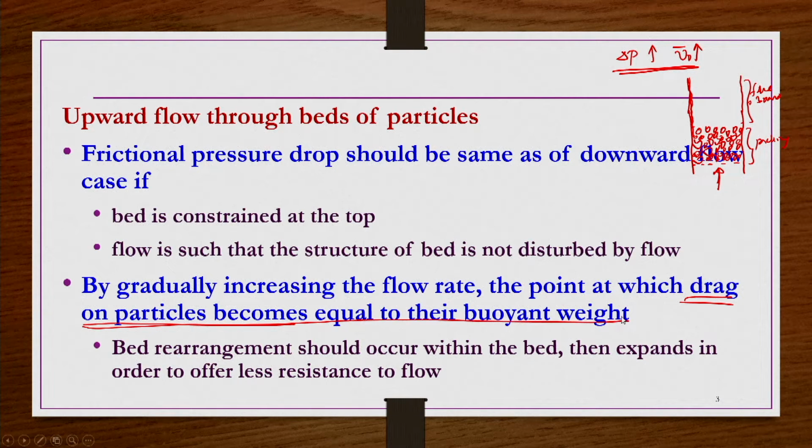After that point, the pressure drop becomes almost independent of the superficial velocity. Why? Because when these particles are moving away from each other, the packing is becoming looser and the bed is being expanded, the drag on particles becomes equal to the buoyant weight of the bed.